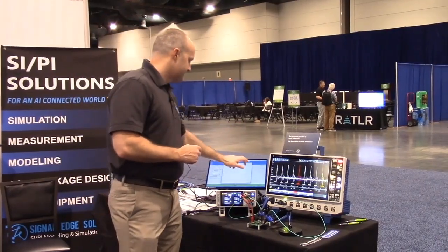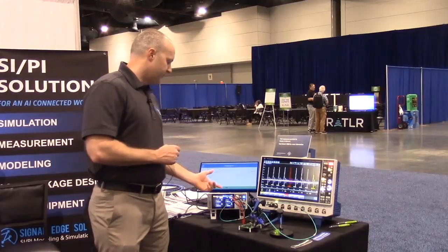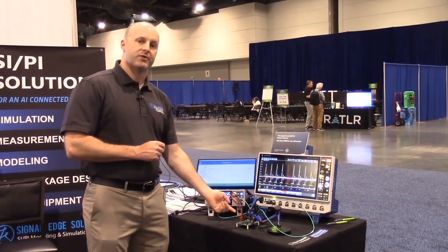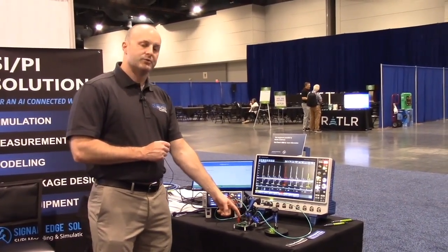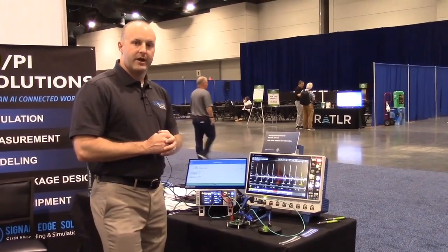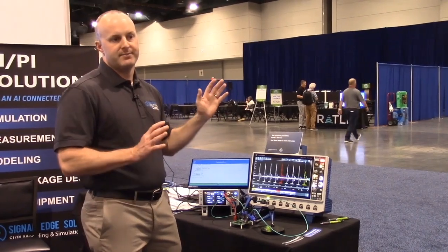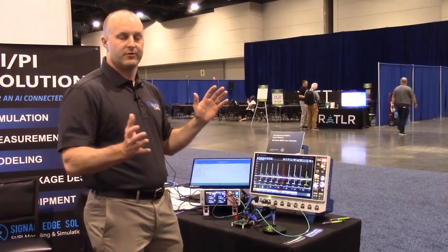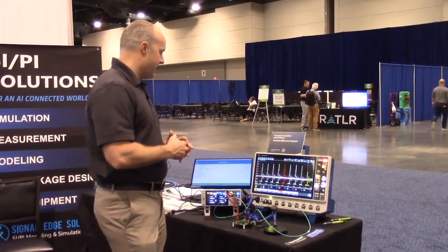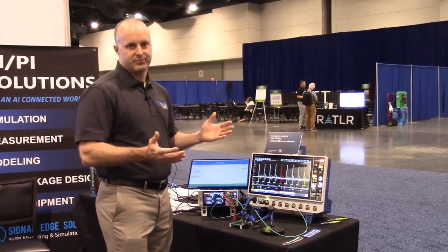So when I hit the run button, you can see it's going to set our output voltage at 12 volts, which is our input voltage into our VRM. Our VRM is regulating out to 1 volt, and we're going to quickly automate and auto scale our initial sweep. Then the scope is going to measure everything after it's set the input and termination impedance for our probe measurement, and it's going to post-process that and show you the worst case response right here, just in a simple click.